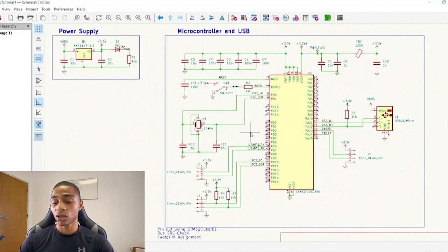And that clock signal will be coming from here, I2C2_SCL. And SCL stands for serial clock, or serial clock line. And just like our crystal oscillator, this just provides synchronization and timing for our communication. And then not only do we have our serial clock line, we also have a serial data line here.